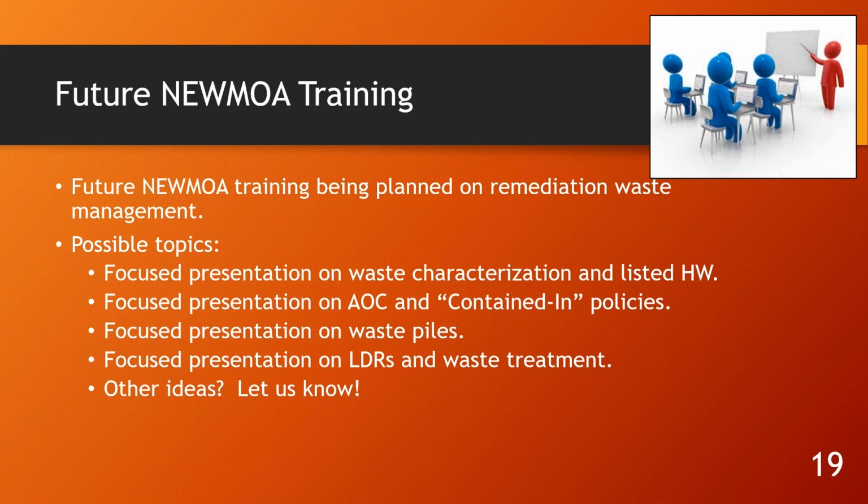Okay. So I'm wondering about rules of thumb to tell these folks so that they don't get into trouble. So you want to try to characterize your soil while it's still in the ground to determine whether there's a possible problem when you dig it up, because you want to know ahead of time about it. And if you dig it up, you don't want to move it very far because that could get you into trouble. You want to keep it pretty close to where it is until you figure all this out. Or like, what are the rules of thumb so people don't get into trouble?